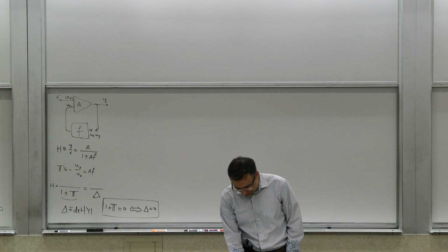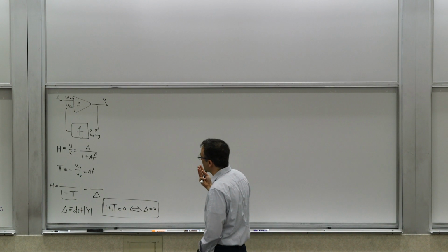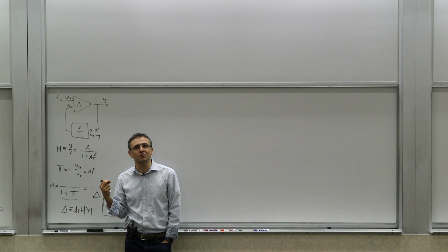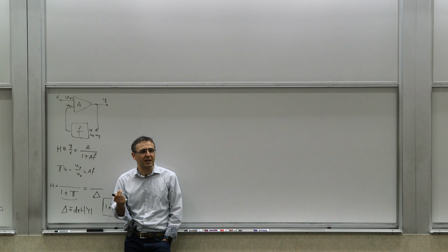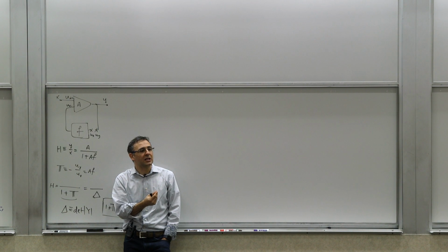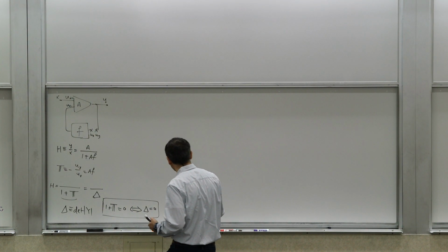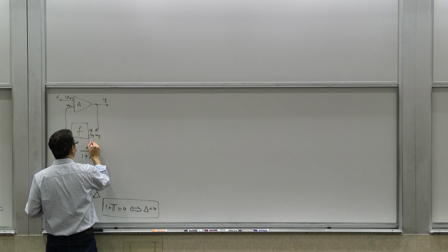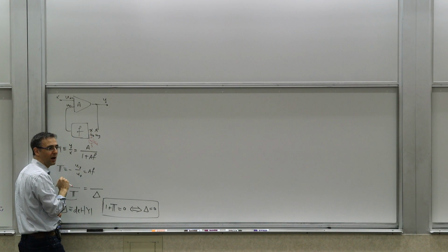So we will do a little derivation here to find out. Now, the second condition is that this should be invariant. The third, it's not a requirement, but it's a desirable thing, is that it should be easy to calculate, at least conceptually. It should be easy to say, okay, this is the procedure you apply to calculate what this loop gain is. Now, for the unilateral loop gain, we had a relatively straightforward calculation. So how did we calculate? We said, okay, one time you apply a voltage source here, you apply a Vx, and you leave this open circuit, and you measure Vy.